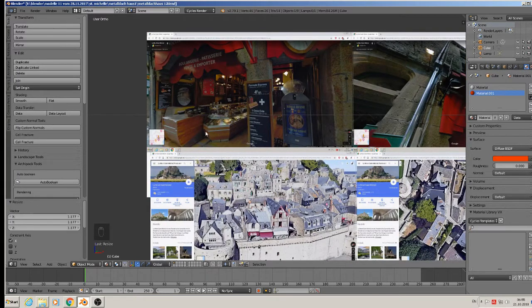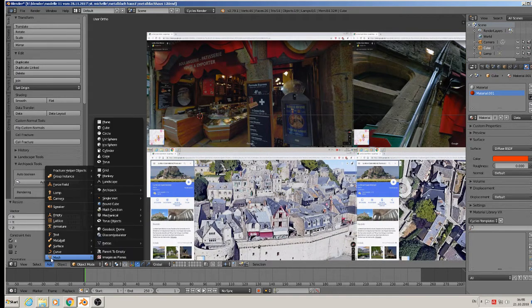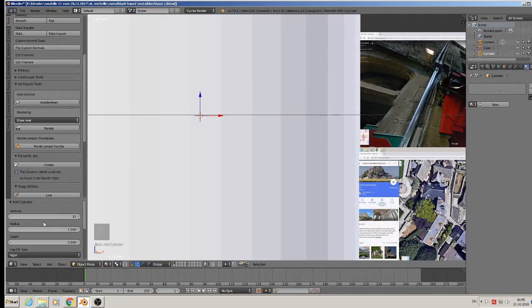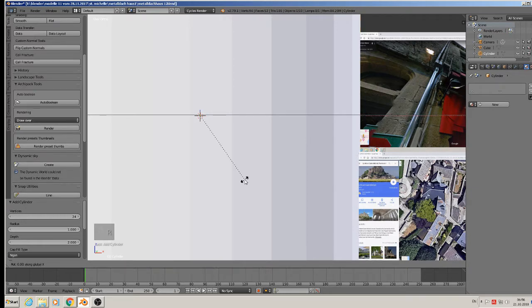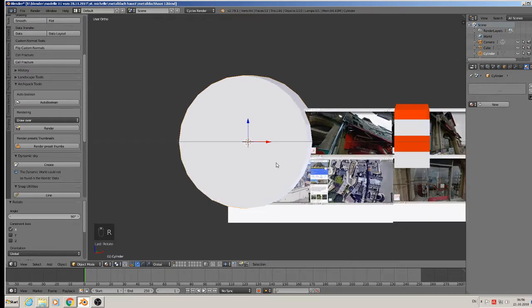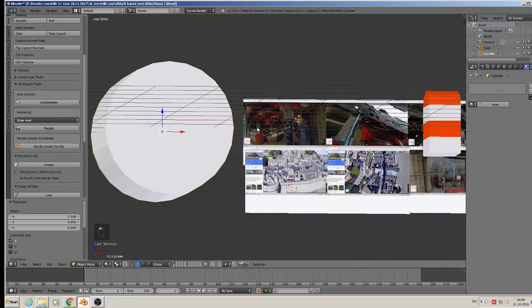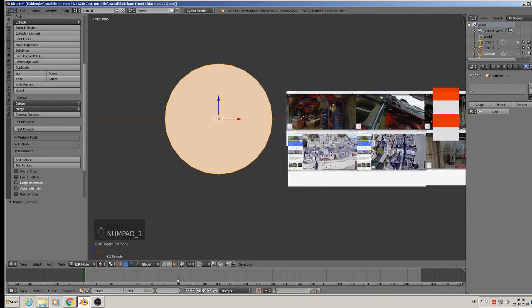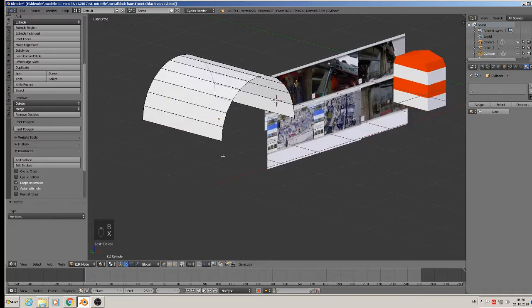Then we need that here. That means add mesh cylinder. We take 24, rotate X 90 degrees, then edit mode, we tap. Then we take border selection with background selection, and delete the down part, so that is left.